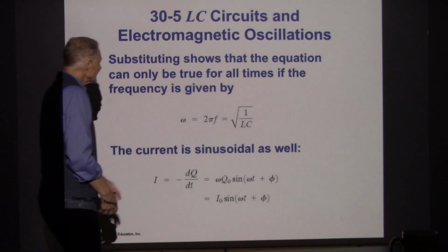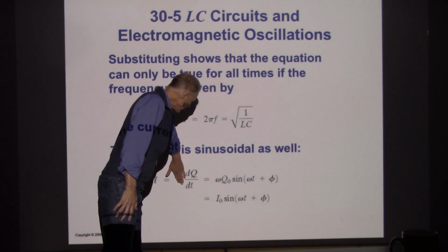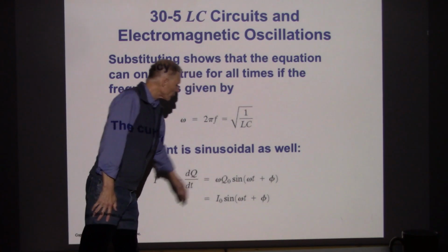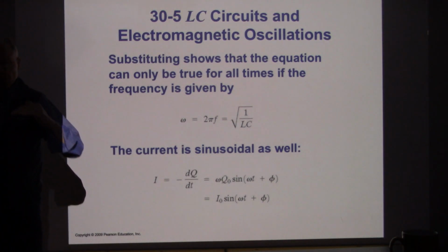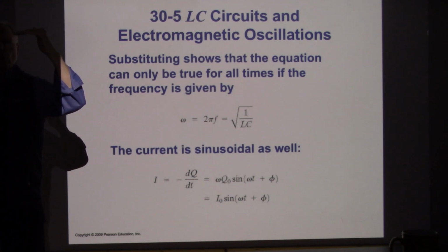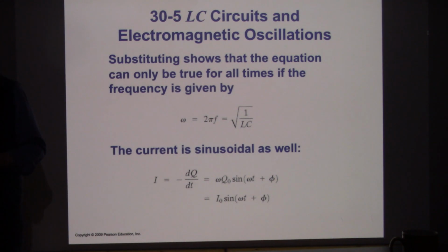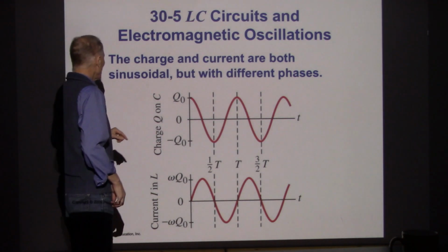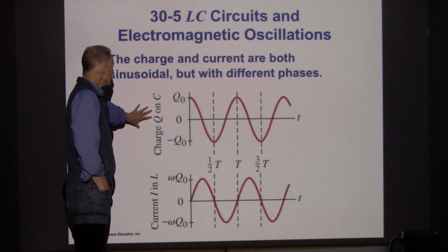So I actually kind of like having the minus sign left off here, and instead have the minus sign show up over here and say that because the capacitor starts out fully charged, when we first throw the switch, the current will be going in the opposite direction to the direction that was used to charge it. Okay, now they're going to use sine functions, so we can deal with that.